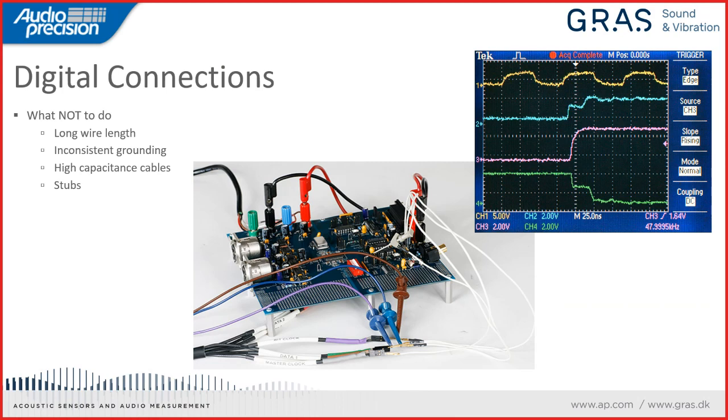So having an 18-inch or longer or shorter cable is still typically much more than the devices were meant to drive. Those cables introduce resistance and capacitance. And one thing you can kind of see on the screenshot from an attached oscilloscope is that instead of having nice sharp square waves, we have some rounding of the leading edge. We sometimes call that shark toothing.